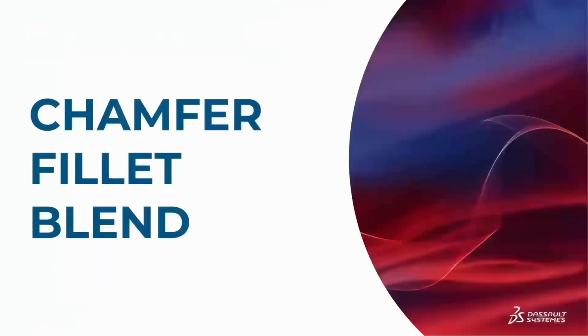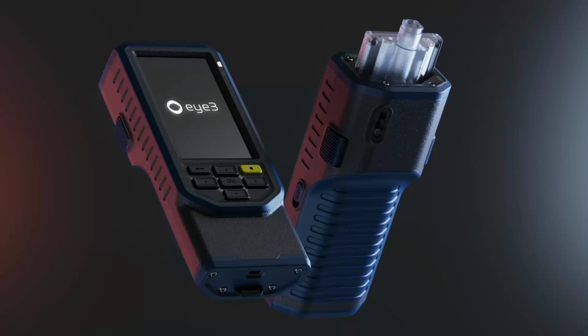Go back in PowerPoint. So I want to jump into more of a hybrid solution here. This is a scenario where we have a couple different quality versions of the same blend. And in this part, we're going to be looking at this particular corner, and we'll jump in SOLIDWORKS, where we have a chamfer that has 2 fillets applied to it, and then it's running into a large fillet radius with some angle geometry as well.